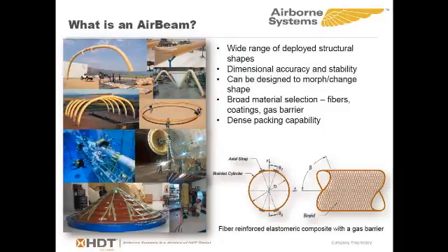We've made tori. We're currently under contract with NASA Langley to build inflatable aerodynamic decelerators. And the picture at the bottom is the IRVE 3, which is a 3-meter diameter aeroshell that was launched last summer. And it was inflated in space, deployed and performed very well. It achieved Mach 10 and demonstrated that it met all the objectives.